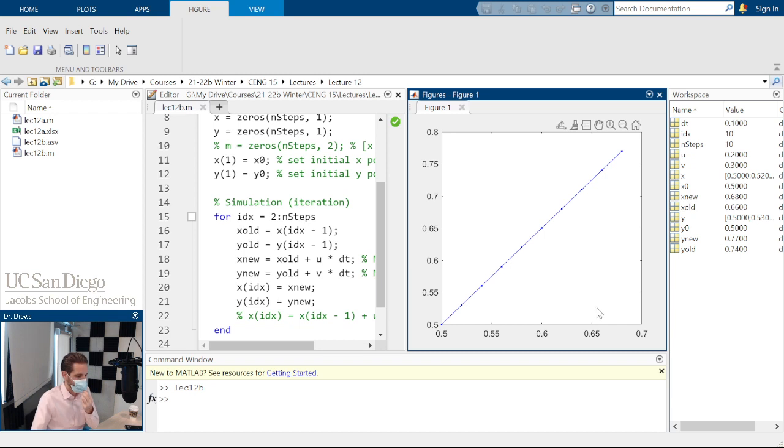So here's the plot that we have. So let's do some of those sanity checks, right? Because as you're building up more and more complicated behavior in your simulations, it's best to do some basic checking. First of all, do we know if the particle started where it was supposed to? Close. We know it was supposed to start at 0.5 and 0.5, and we know at least one of the two endpoints that we have here is at 0.5 and 0.5. So it seems reasonable that it probably started there and went in the other direction.